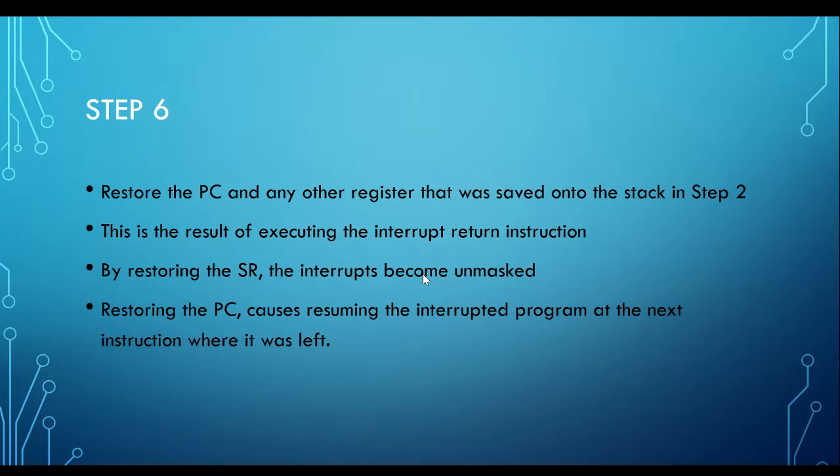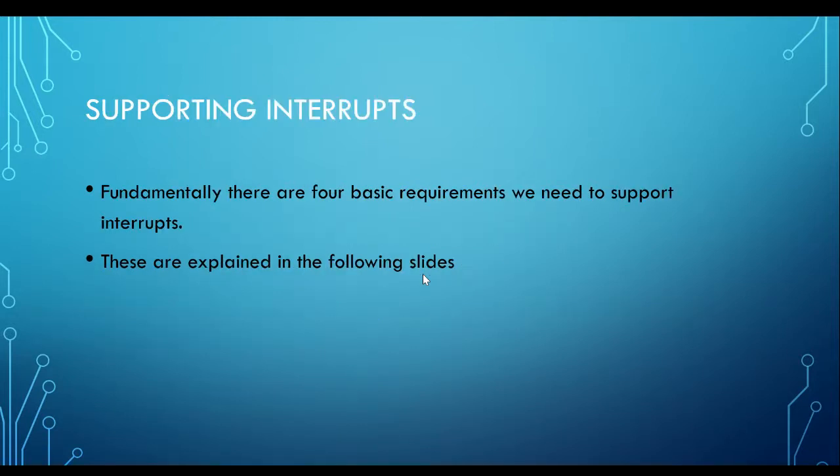And the final one is how do you go back to the state before the interrupt was requested. So you get back whatever you have loaded onto the stack. Let's say, for example, the PC value and the carry bit, negative bit, whatever bit that you have previously saved in the stack register. Take it out, put it back to where it belongs. So it's actually restoring the state of the computer before the interrupt was called.